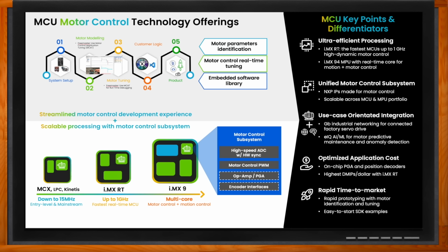This is what we are trying to achieve. The power inverter will change in size because of the motor it's driving, depending on what the motor power level requirement is, but the MCU should stay the same. The only change within the MCU will be the software and the firmware for that particular controller.